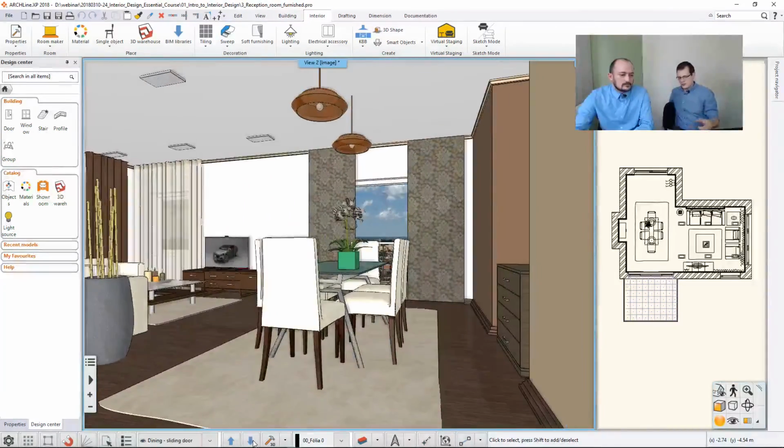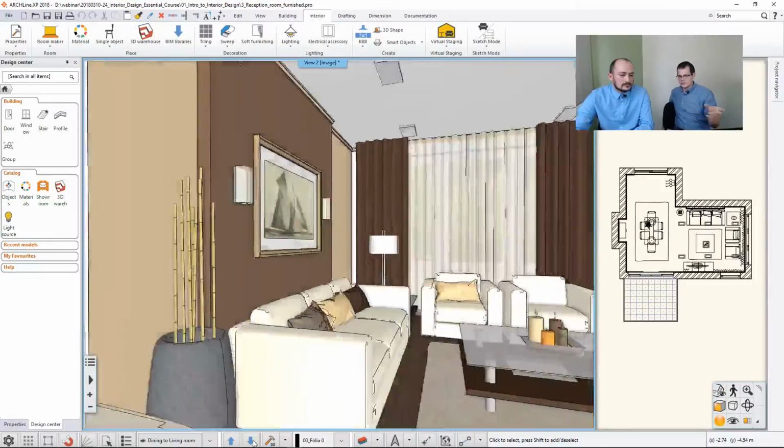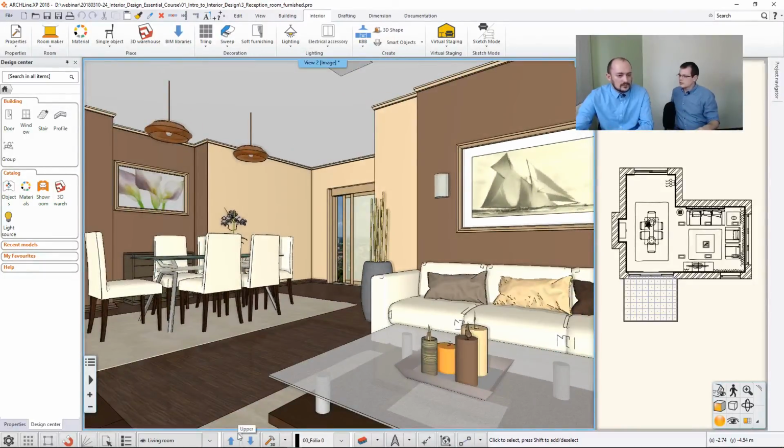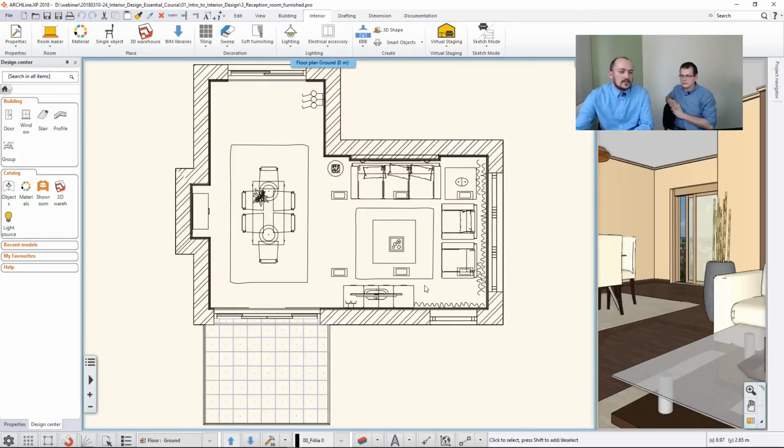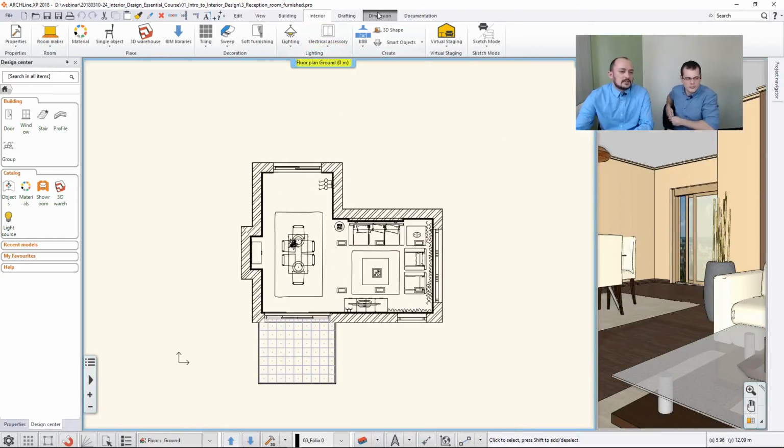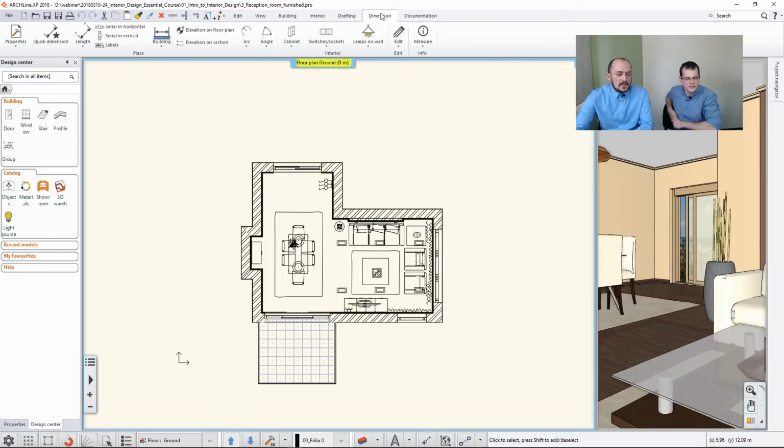So now what do we do? Do we work on the 3D or should we focus on the 2D view? Now for the 2D documentation, I will use, of course, this here. So I just enlarge the 2D and I will add details to this using the dimension tools. The dimension tools are, again, a whole palette of things that you can use, a lot of things measuring angles and elevations and things like that. I will actually create an elevation drawing also.